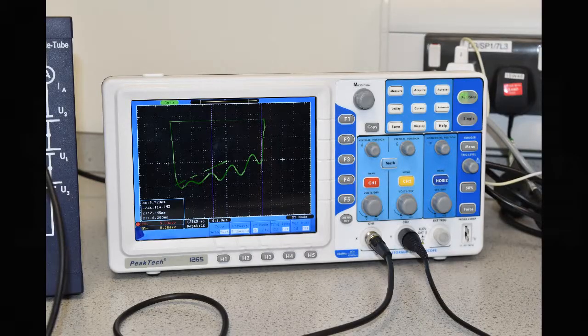So in order to use the oscilloscope, set it to the XY mode, which plots the coordinates on the screen. Do it by pressing the horizontal button and changing the setting to XY. A dot should appear on screen, press start on the control unit.